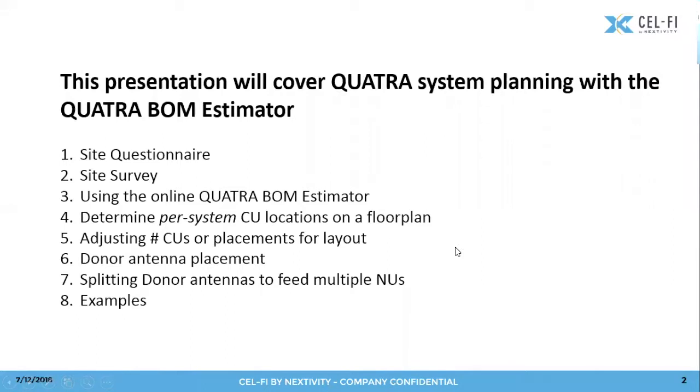All right, the material that we will cover today, I'm going to start out with a site questionnaire, something that a lot of you are used to handing your customers because you need to get some details, of course, about the project at hand. And then visiting a site, because there's nothing better than being there and actually knocking on the walls to see if there are hollow walls or solid walls, seeing how they use the spaces, etc. Hopefully measuring the signal levels and looking for good donor antenna locations if you're going to use an off-air signal to feed the system. Then we will get into the estimator tool itself and determine how much equipment is most likely required for the site.